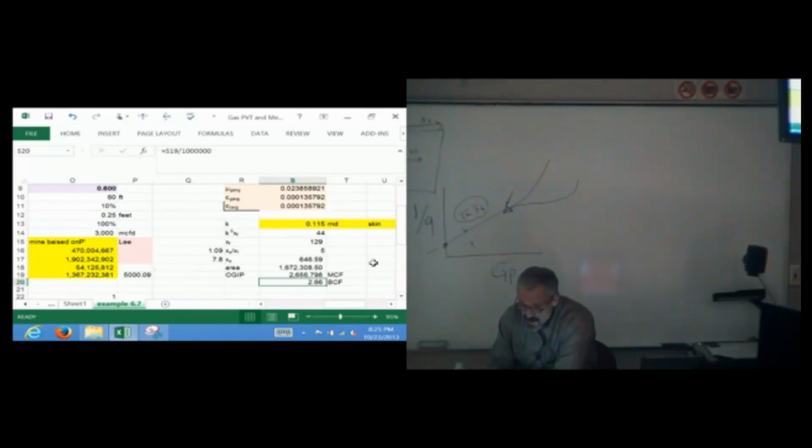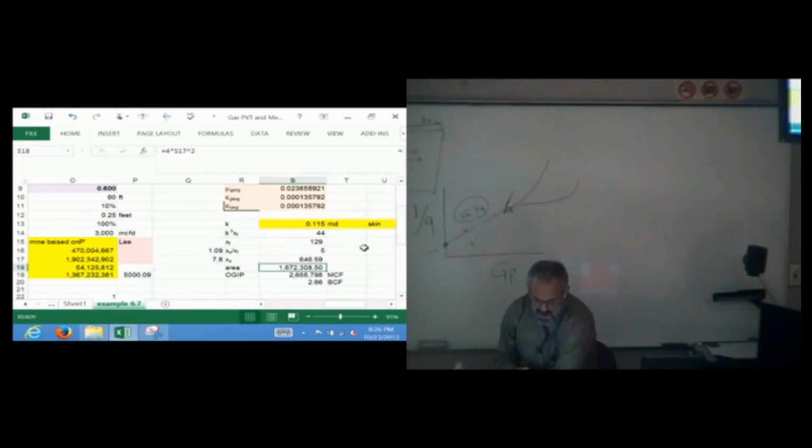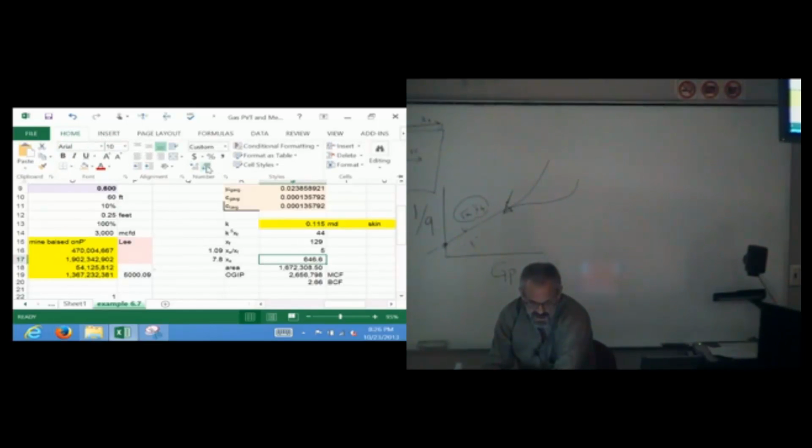Which one? I can't hear you. X sub e? X sub e is x sub f times x sub e over x sub f. Okay? See how the x sub f's cancel? And you end up with x sub e. The x sub e over x sub f I picked out on the family of type curves. That's what my data was climbing up, the x sub e over x sub f of 5. My x sub f I calculated as 129 feet. So I multiply those two together and I get x sub e of 647 feet once I get rid of the pennies.